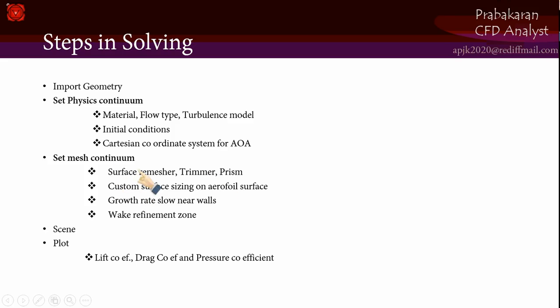So I will select some mesh modelers, and then I will set some custom surface controls on the aerofoil surface so that I can capture the physics near the aerofoil accurately. For capturing the flow over the aerofoil accurately, I am choosing these two, and a wake refinement zone in order to find out the wake developed in the flow.